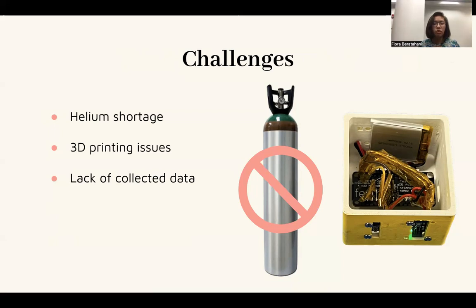Additionally, we also only had one chance to print our structure, so we had to work around a few problems. One of which was that there was no space to connect the components using jumper wires. So we had to solder wires directly to the microcontroller and sensors. Also, we had to remove the lid of the banana at the launch because the temperature sensor was providing inaccurate measurements.